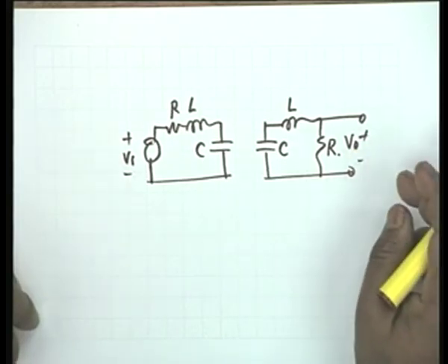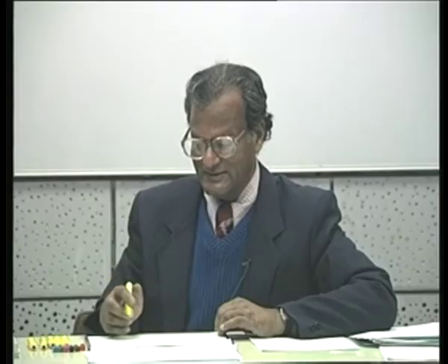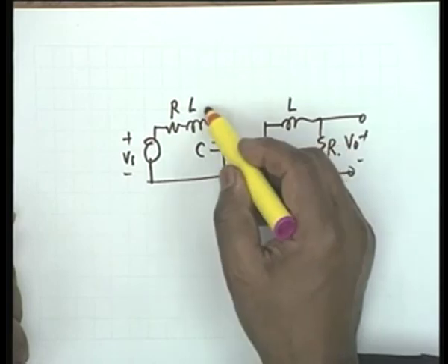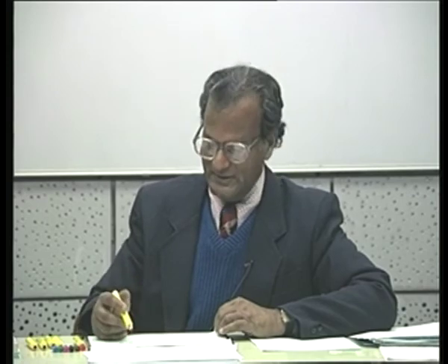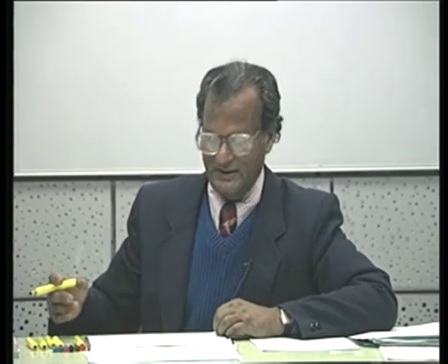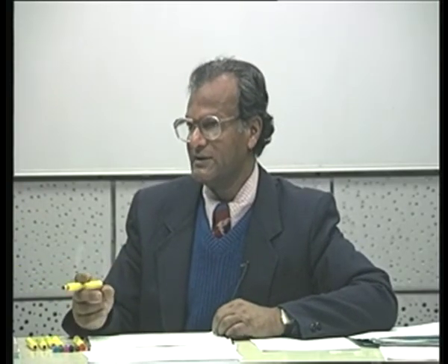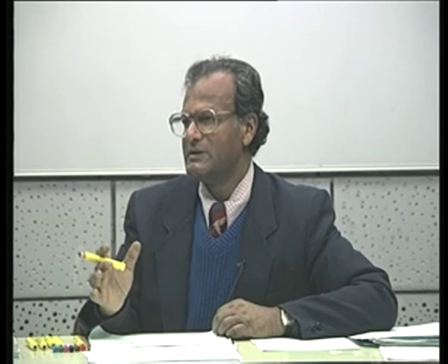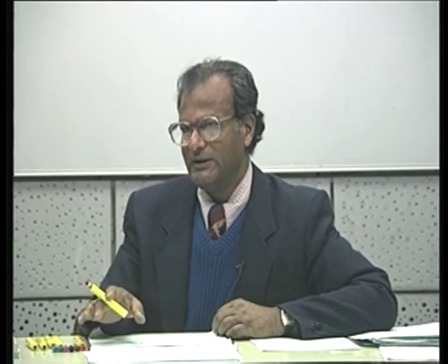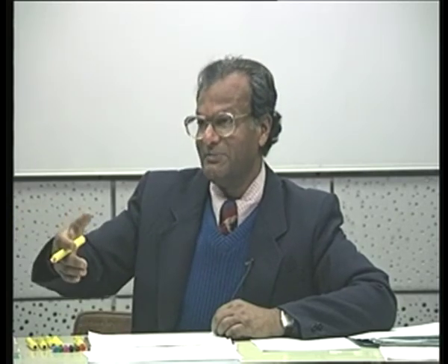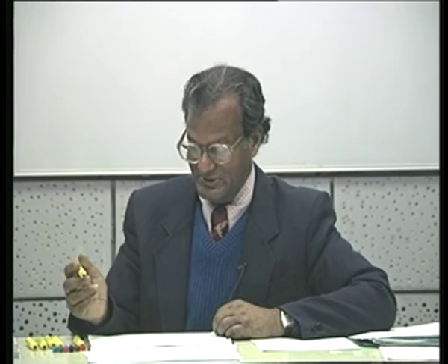Now, obviously, if they are not coupled to each other, that is, this is shielded. You know what is a shielded coil? It's surrounded by a non-magnetic metal. So it shields the magnetic field. Magnetic field is all inside. It cannot couple to anything outside. Most of the coils that you see mounted in radio frequency and lower frequency apparatus are all shielded, because otherwise they are going to couple with anything that is nearby and cause havoc. So they have to be shielded.